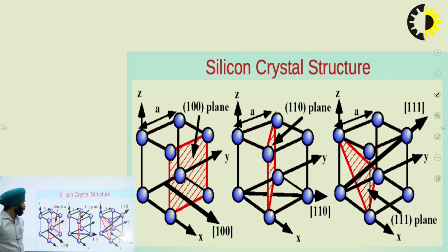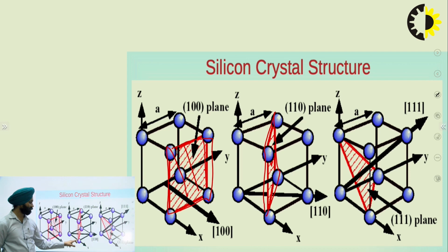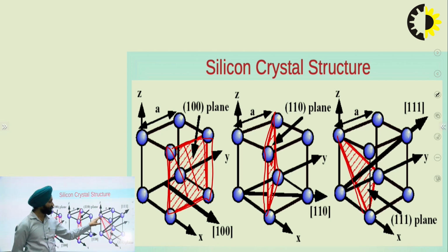So this is the way that we can see. This is the one at the plane where the atoms are joined, and these are at this plane which is the 1 0 0. Similarly, body centered has one plane in between, so the maximum density would be at the diagonal planes. And the last one, when there is a face centered, then the maximum density is between this atom and this atom.